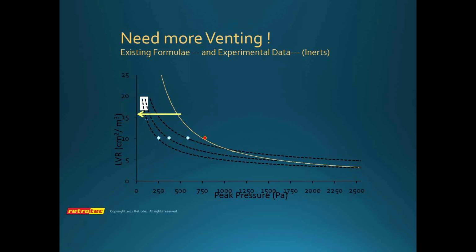So the new FSSA formulas have been well vetted, and experimental data has been taken over a very wide range of pressures. Moreover, the data was taken in such a way that when you do a door fan test, you can actually use that door fan test data to properly predict the peak pressure. One of the missing links that we had before was when a peak pressure was measured, it didn't really relate to how we measure enclosure leakage. So the two weren't kind of in sync.